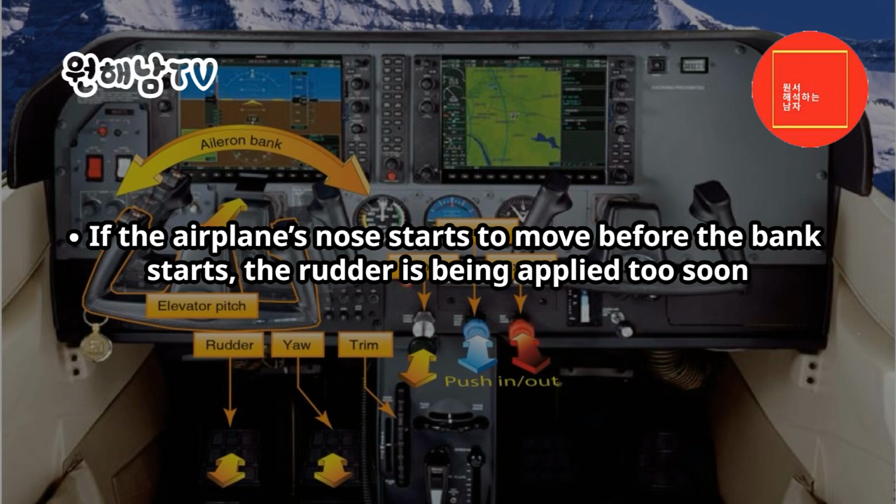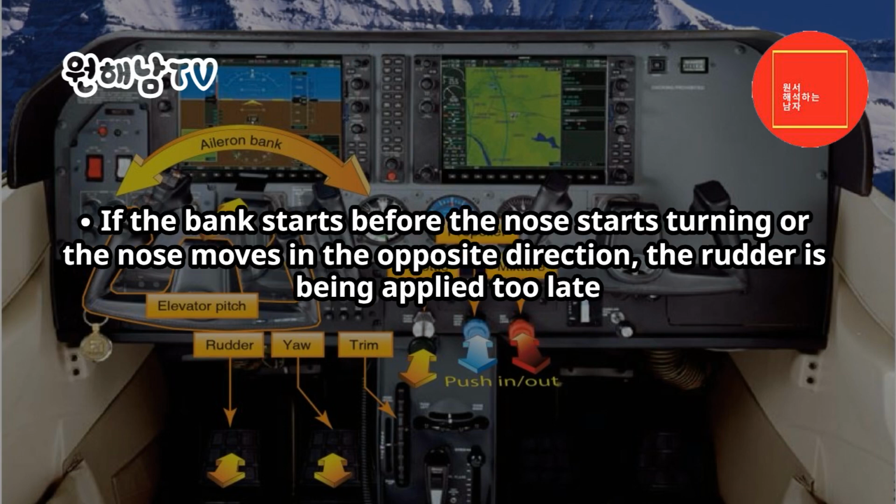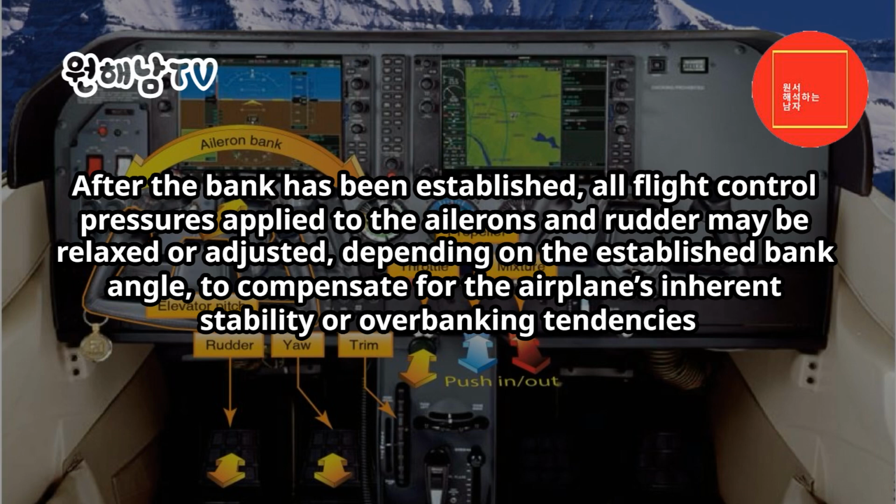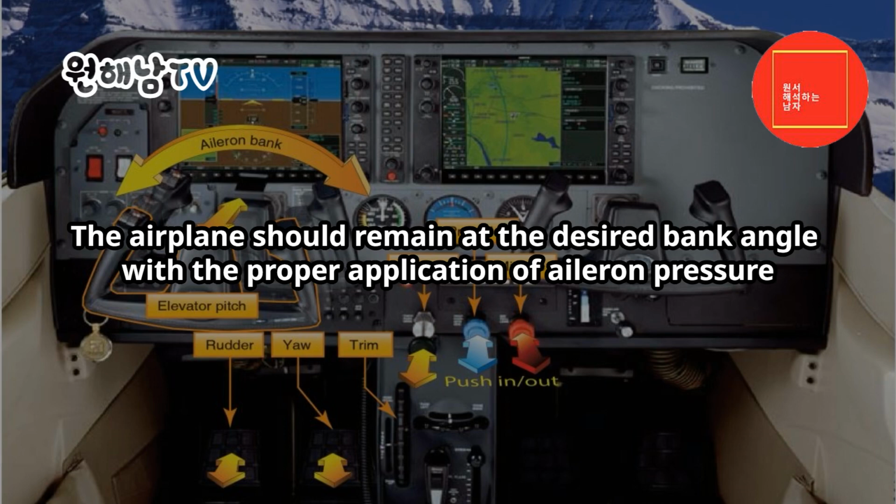If the airplane's nose starts to move before the bank starts, the rudder is being applied too soon. If the bank starts before the nose starts turning or the nose moves in the opposite direction, the rudder is being applied too late. If the nose moves up or down when entering a bank, excessive or insufficient elevator back pressure is being applied. After the bank has been established, all flight control pressures applied to the ailerons and rudder may be relaxed or adjusted, depending on the established bank angle, to compensate for the airplane's inherent stability or overbanking tendencies. The airplane should remain at the desired bank angle with the proper application of aileron pressure.